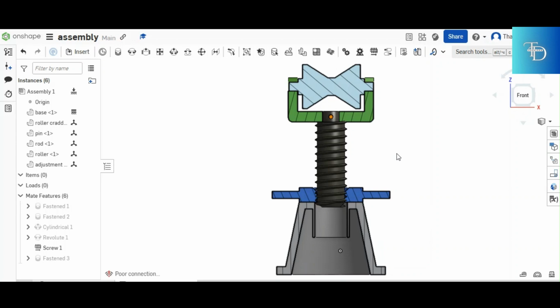There are things that you do not section on engineering drawing. First being this one, the threaded surface, you do not section the threaded surface. And then the web, something that has a web in it. When you get to that part whereby there is a web, you do not section the web. Those are the regulations. Those are the rules.